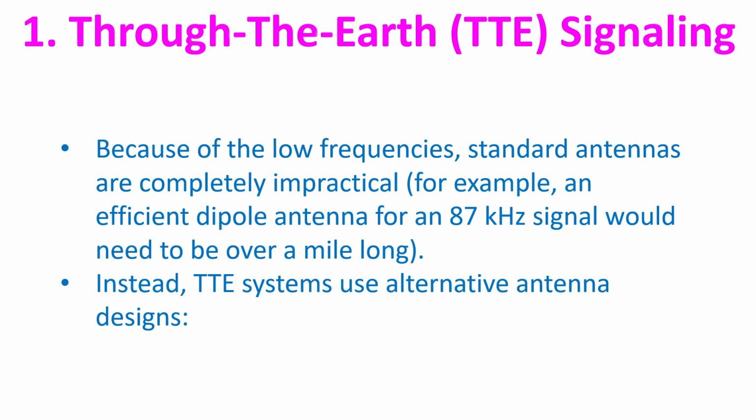Because of the low frequencies, standard antennas are completely impractical. For example, an efficient dipole antenna for an 87 kHz signal would need to be over a mile long. Instead, TTE systems use alternative antenna designs.